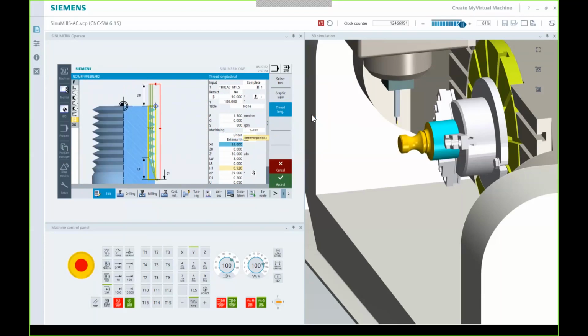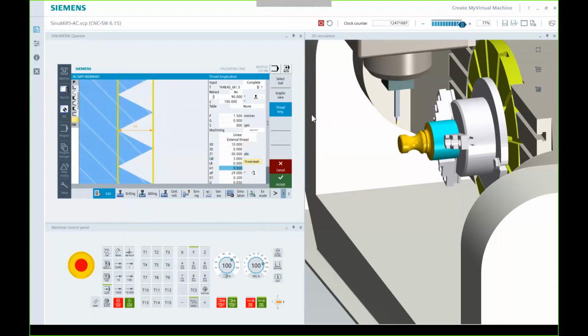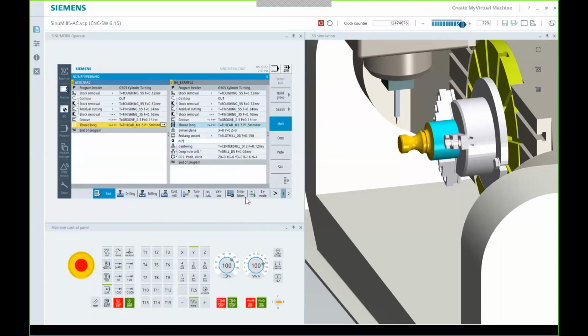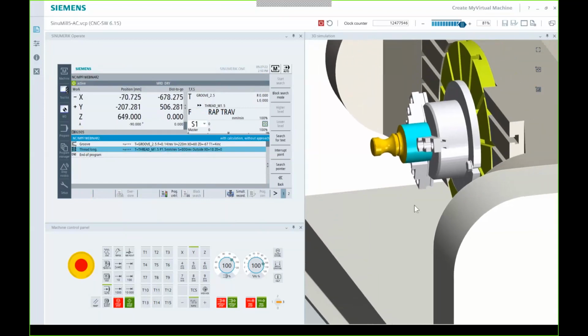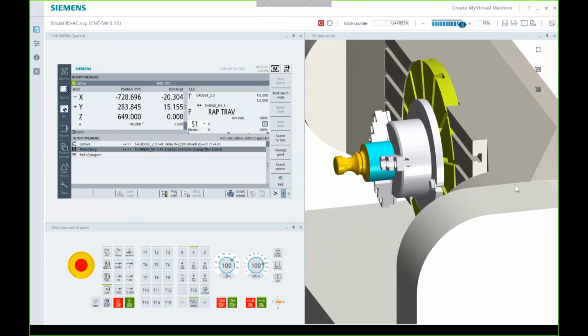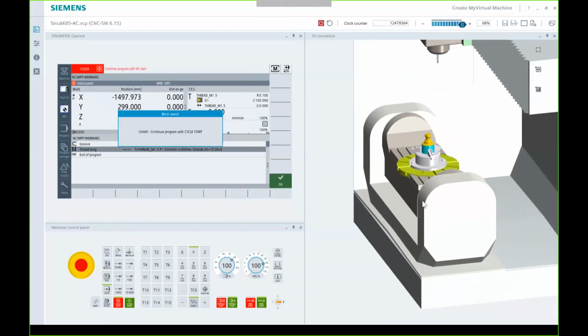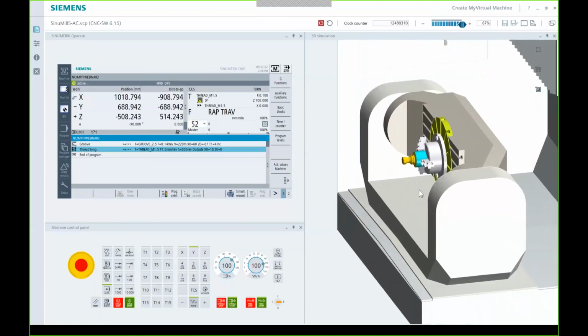it. We're doing an external thread. We are at 18 millimeter OD, and we're doing 30 millimeters of thread. My thread height is 0.92 millimeters, and it's at 20. So now we go ahead and execute this, as long as I didn't mess up any numbers in there. It should come in. I hit a bunch of wrong keys, so I may have messed up my threading cycle. But we'll find out real quick here.